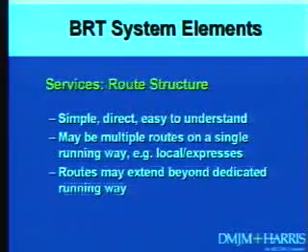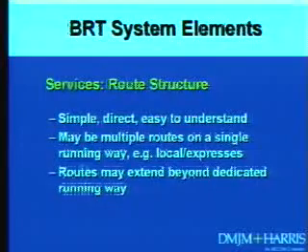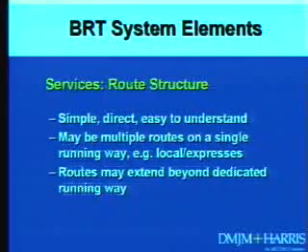In Ottawa, which has the best busway system in North America by a long way, their bus system operates where they take about 80% of their customers with one-seat rides. That is, no transfers. 80% no transfers. They do that by having these buses go out and circulate through the network to the neighborhoods, pick up their people, get on the busway, and express to downtown, or very few stops. There are other buses on that busway that are stopping at every stop and picking up people that are transferring from other buses that are going over the top of it. So there's all these different services on that same facility.